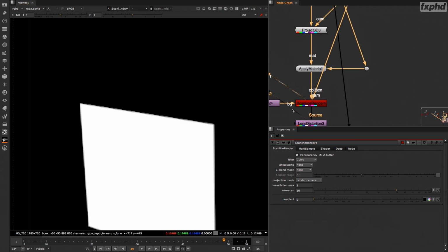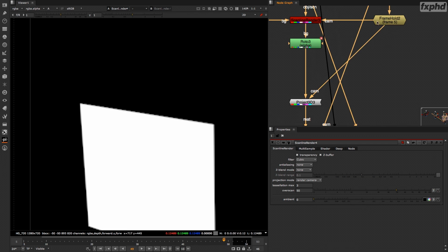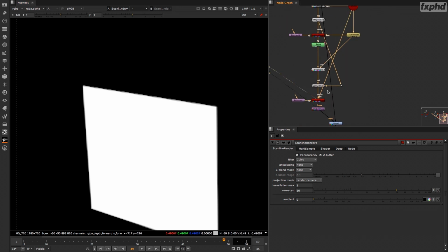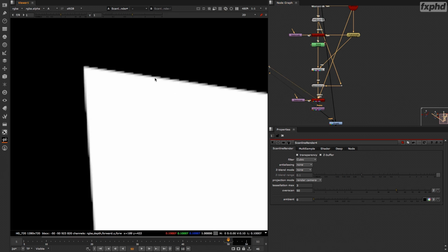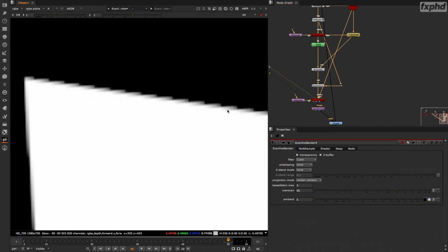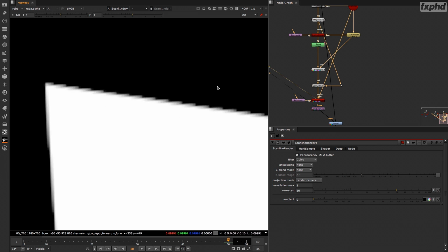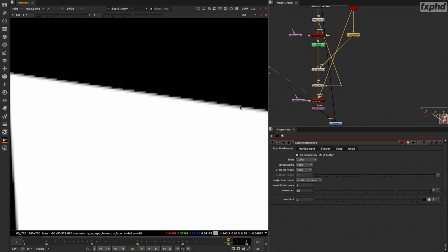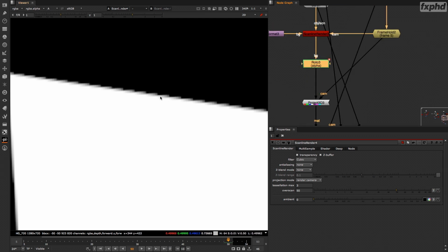and that's because we are projecting on a frame, which is frame 5, where the geometry is pretty far in the scene. So when the second camera is filming back the projection, the geometry is getting very close to the camera and the actual roto is lacking a lot of resolution. So there's one easy trick to fix this if you notice after your roto that you still need a bit more resolution like that.